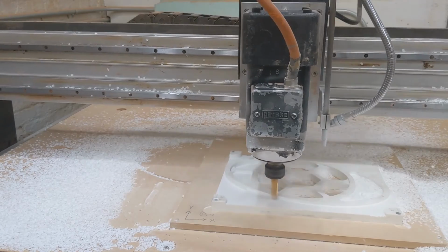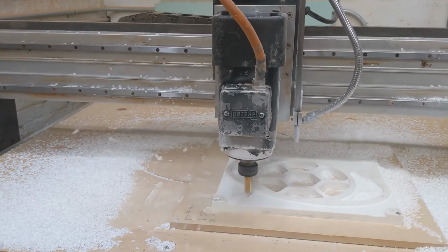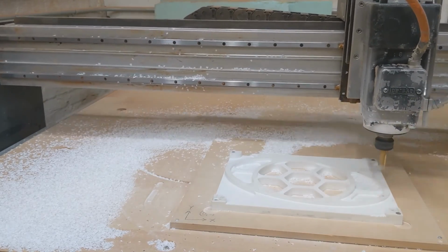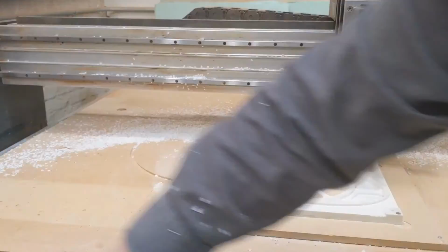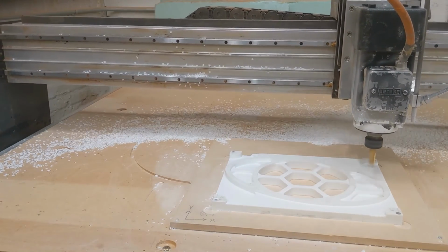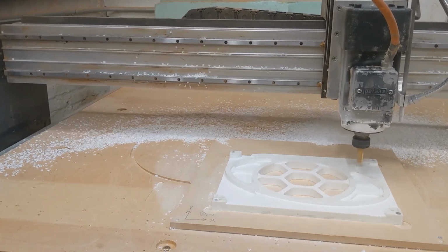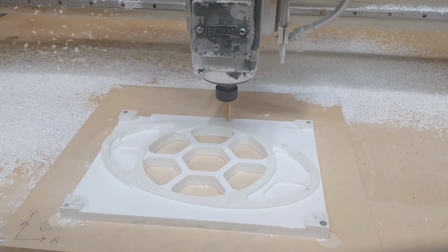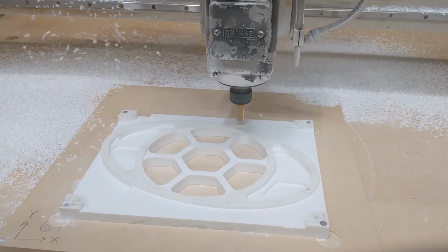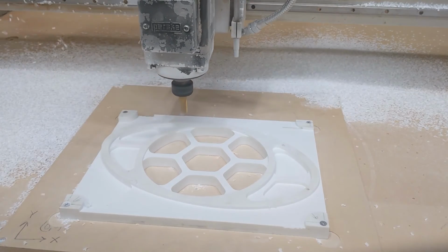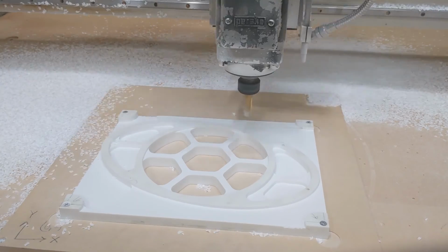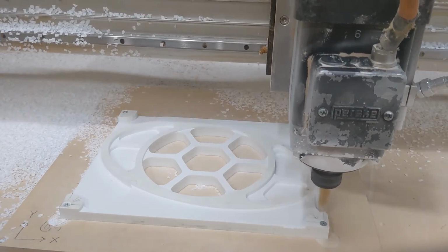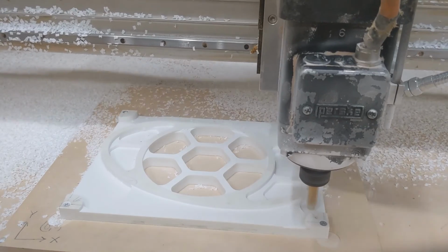These high-speed or so-called high-speed tool paths that are generated by modern CAM software like Fusion 360 are really optimized for a pretty narrow width of cut and much deeper depth of cut. So like machining steel on the big fancy new CNCs, you're going to have maybe a 32nd of an inch width of cut and maybe a full inch or 2 inches depth of cut. So you can keep that in mind. So 60 inches per minute, good place to start.